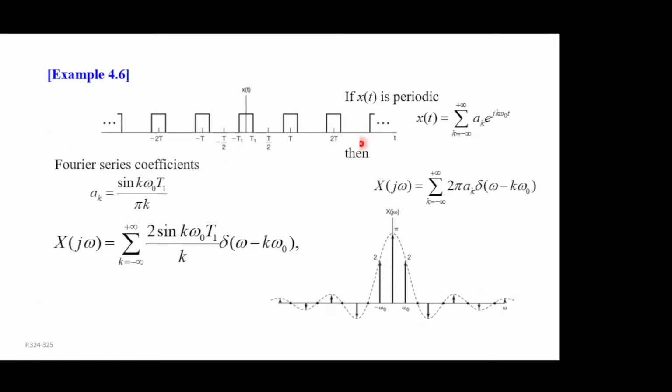Because it doesn't satisfy the Dirichlet condition, the Fourier transform is a bit funny. We get infinity everywhere. It's a whole bunch of delta functions, but we are pretty easygoing on what we allow to have a Fourier transform. Even the delta function, we think they are valid things. Okay, so that's a digression.